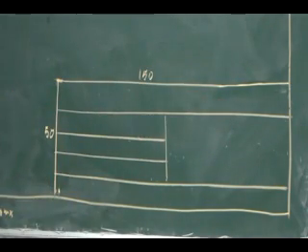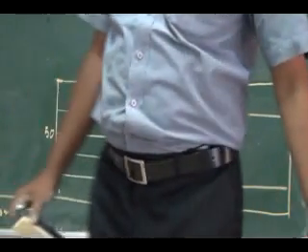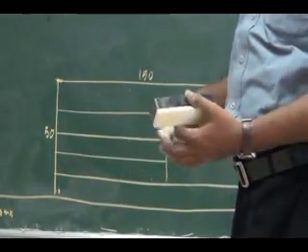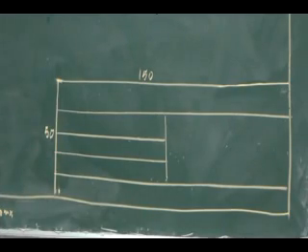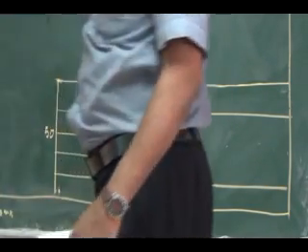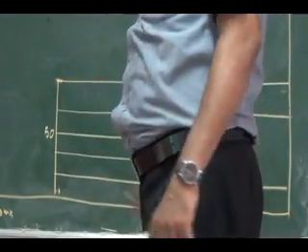So what are the details we are going to write in this title block, you will see. This title block as such, what I have drawn here, should be in HB pencil, in dark. The darkest pencil you have is the HB, so using that you can draw the layout, you can draw the title block like this.